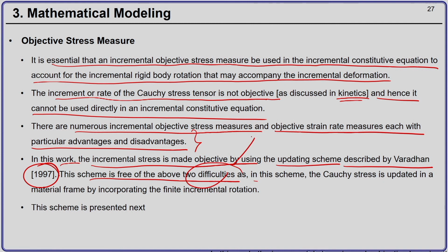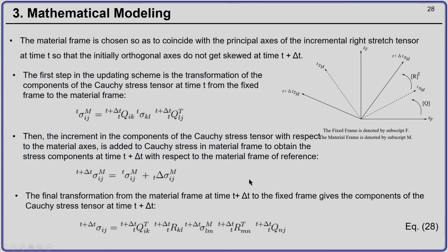This scheme is free from the two difficulties mentioned above. It does not have those shortcomings, and the Cauchy stress is updated in a material frame by incorporating the finite incremental rotation. So even if the rotation is large, it does not matter. We just update the Cauchy stress in the rotated material frame. We describe this next.